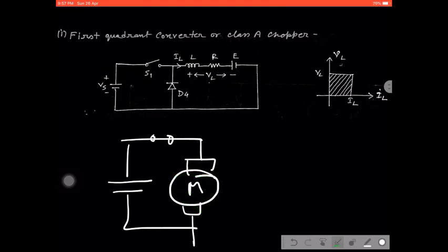And we know when the motor starts moving, the armature conductors start cutting the flux developed by the field magnet, and it produces an amount of back EMF inside it, which stands for EB. If the supply voltage is this one, the EB should be this one. It's a normal motoring operation. I just want to recall it for this purpose.